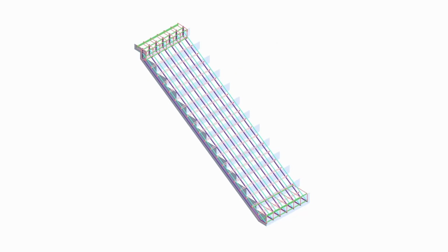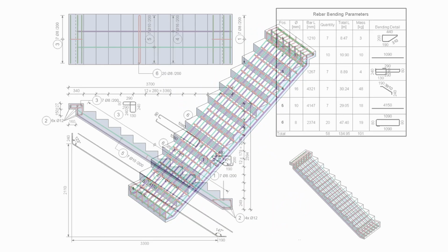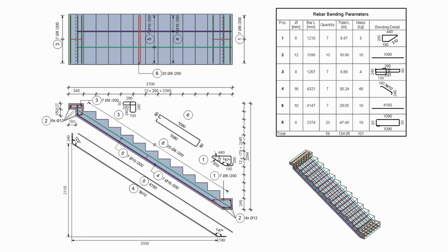And that's how you can reinforce a stair directly in 3D, just by picking the constraint targets. Even angled reinforcement along the stair run can be created easily without dedicated 2D views. I've attached the Revit file used in this video if you'd like to try the workflow yourself.